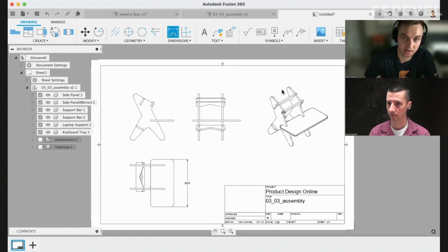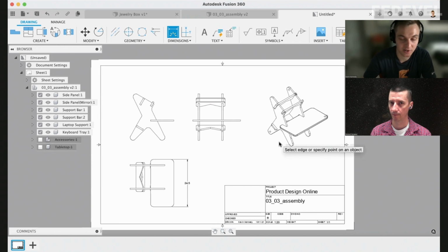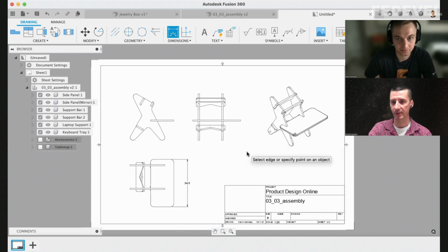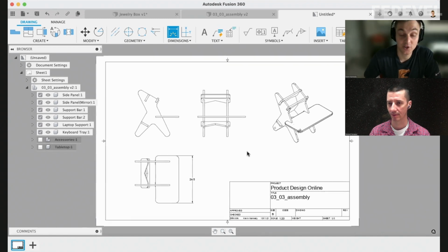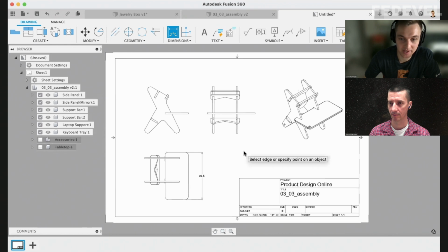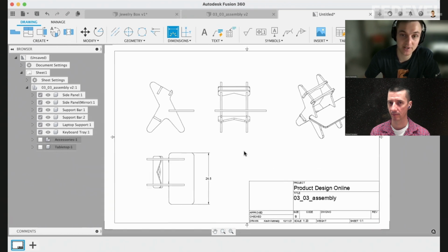That's more of a best practice anyway in manufacturing drawings, because typically in an isometric view things can be skewed a little and it can be hard to understand. I have never actually seen dimensions on these 3D views. You're not supposed to. I like to call that out because I think some folks, especially on the hobby side, don't recognize that or maybe haven't learned that yet, and then they think it's just not working. It calls that out for you when you try to hover over it.